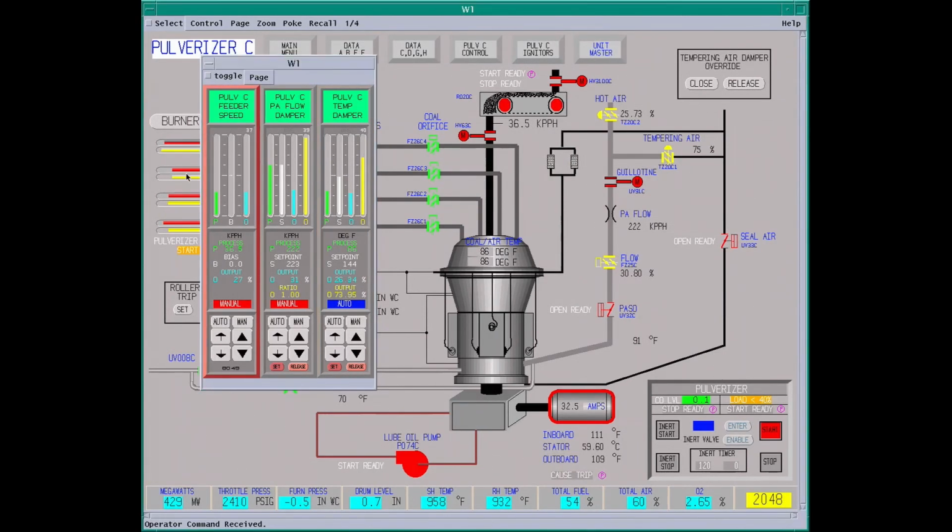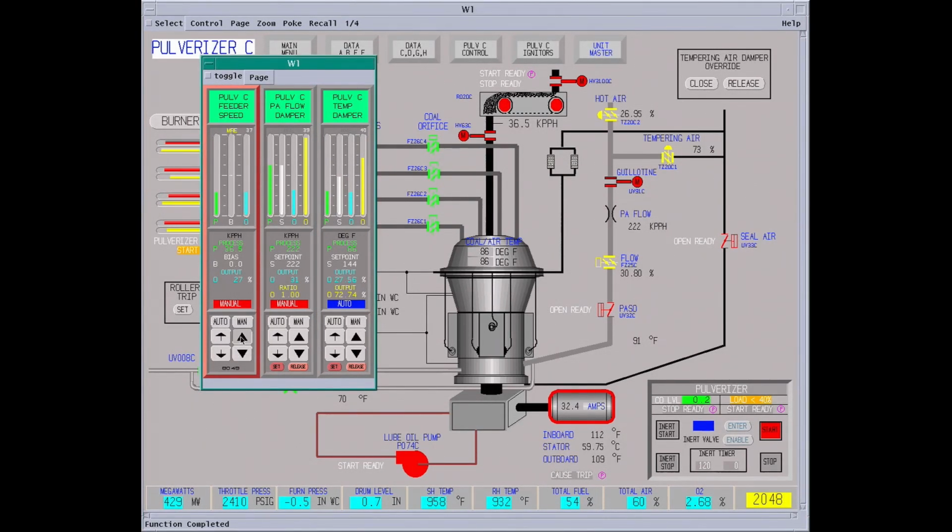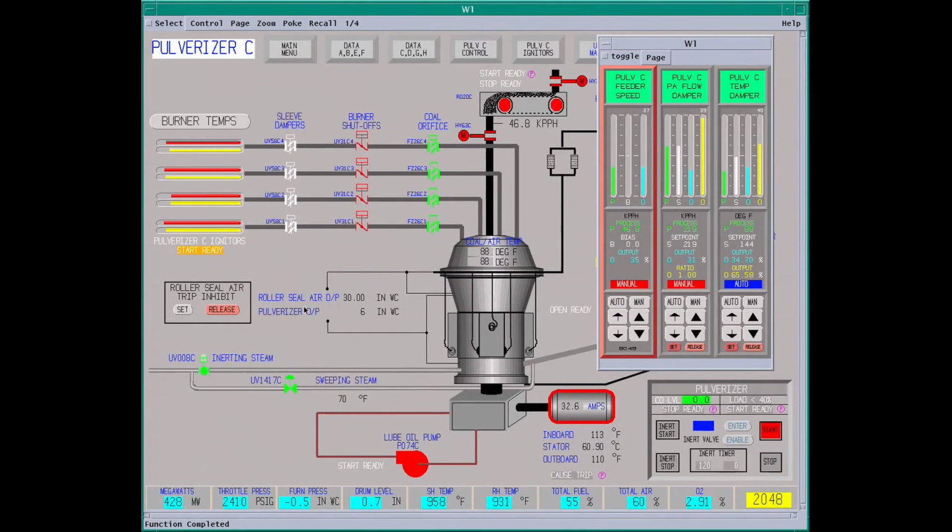Okay, we need to get this thing above 40% load. Also, if you lose an igniter right now, you'll trip it. Once you get above 40, you have to lose a second one for it to trip. Okay, the light went out. Plant should start moving again. Need to do about 5 clicks on fuel. About 5,000 pounds at a time. To watch a DP.